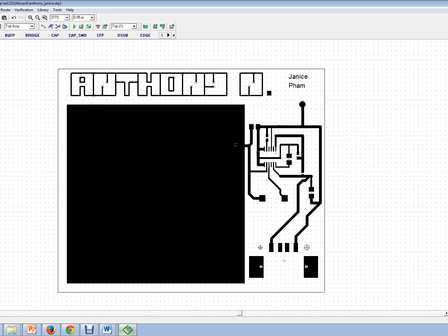Now in order to get all these boards rapidly made, the assembly tool, which is called integrator, needs an official board outline, and this top assembly rectangle doesn't do it. So in order to do that, we need to place a board outline.